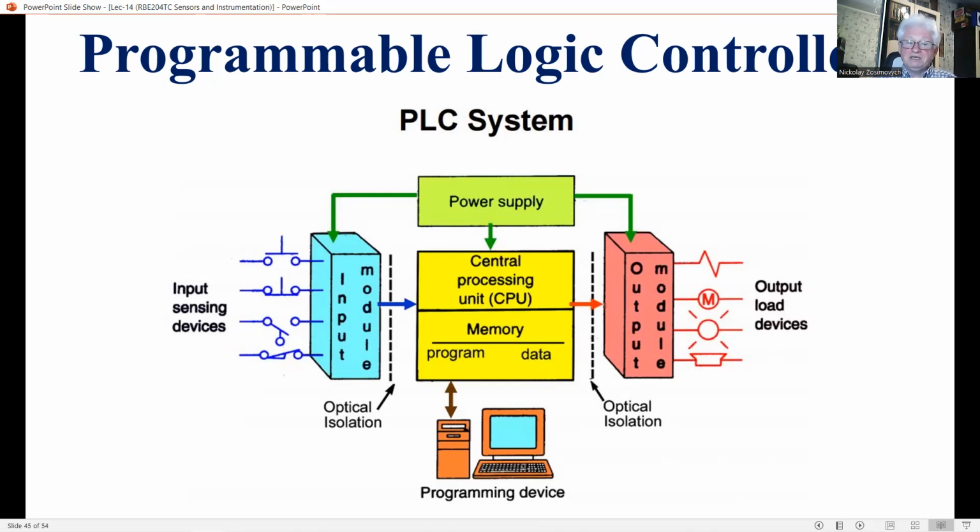PLCs are typically used in factories and process plants to connect input devices such as switches to output devices such as valves at high speed at appropriate times in a task, as covered by program or ladder logic. Examples of such tasks include sequencing the production line operations, starting a complex process plant, and activating the local controllers in a distributed control environment.